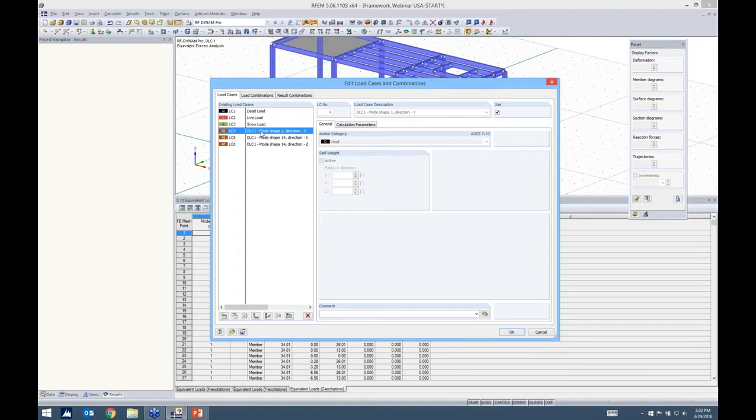But now we have some mode shapes, and we have kind of a special case here for this structure because we had those two dominant modes, mode shape 1 and 14, for all of our X, Y, and Z directions. This is pretty rare. Usually you're going to have several mode shapes for all directions in order to reach that 90%.